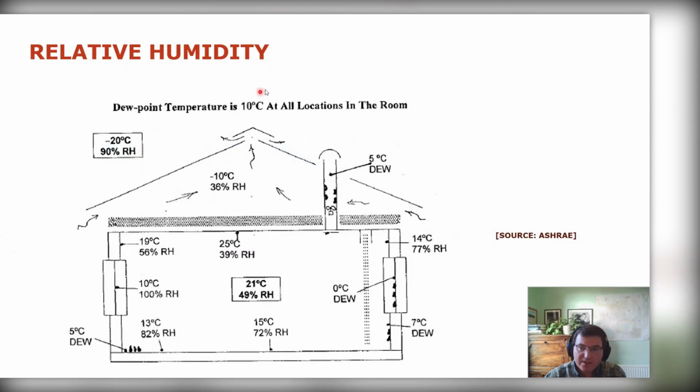Okay, so relative humidity and dew point, why are those important? Well, the reason relative humidity is important is because that gives you a good feel for what will be happening to some liquid or some moisture that's already in the air. So if the relative humidity is low, it shows that there's a lot of capacity for this air to be taking up more moisture. So more moisture can evaporate and change from liquid into a vapor, and therefore we can dry things out that way.